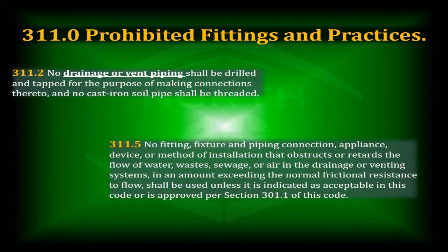You go back into some of the older sewage systems, and basically without fittings, holes were cut in the side of the sewage systems and pipes were stuck in, and then they were welded around. And if you go down through there with a sewer service camera, you'll see these pipes that are just stuck way out into the sewage system, and it catches stuff as it goes down through the sewage system, and it can cause stoppage, retard the flow.